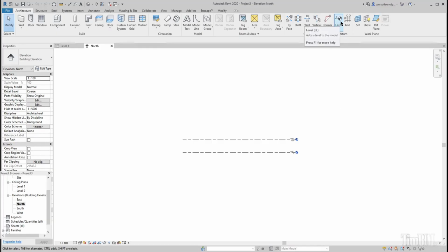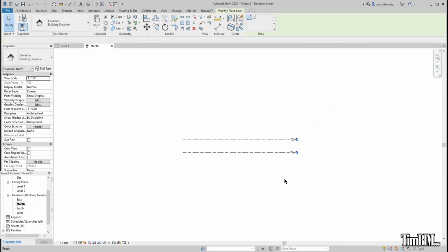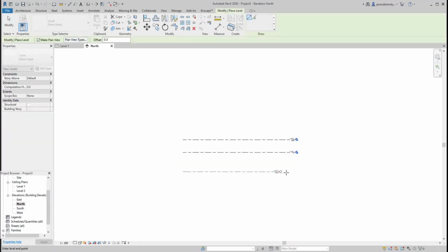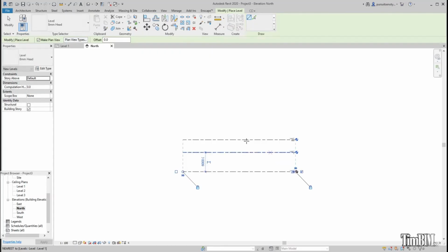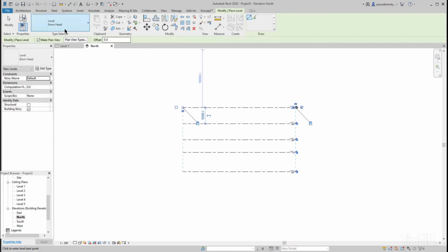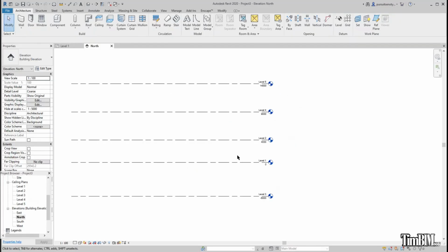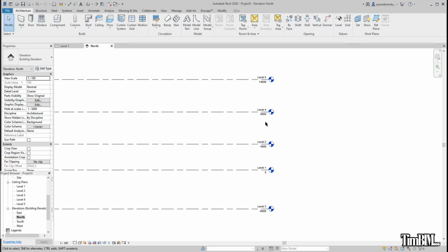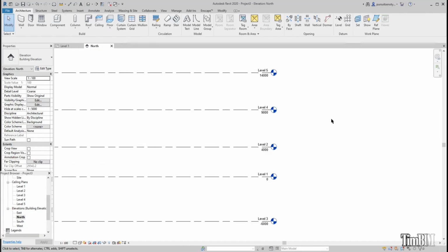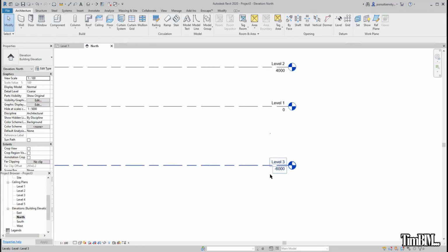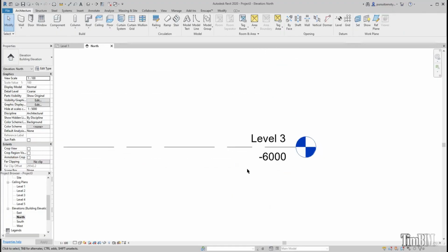This is where you will see your levels. So you click on your levels, then you come here and draw your levels. You click and draw your levels. After drawing your level, you press the escape key, or you come to Modify, the select tool. You click on Modify, then the level tool that you picked will be deactivated. From here, you have to customize it to meet what you want.